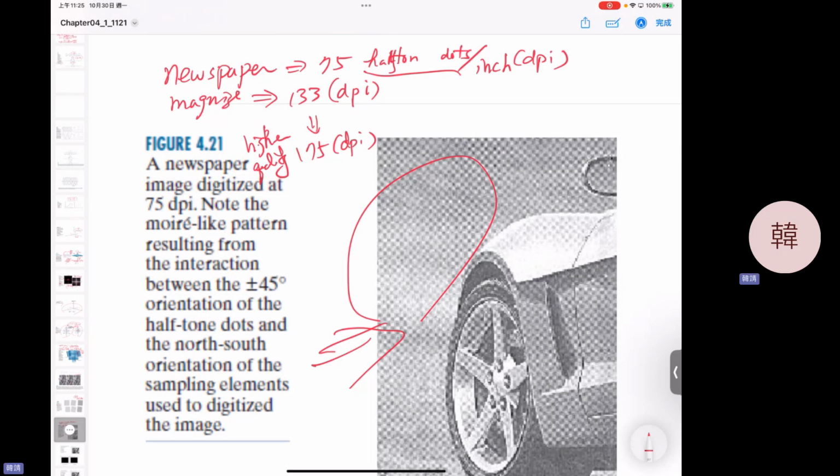As long as you see a frequent pattern repeat and you transform into the frequency domain, it should be a later chapter. We have a lot of different filters to design. And you see each one in the frequency domain, there's some energy there and some spike, white spot there. What's that? Because of the Moire pattern, because of your low resolution. That's fine. Immediately you just remove those white spots in your frequency domain, and the image becomes very smooth. In your computer, you can do it immediately.